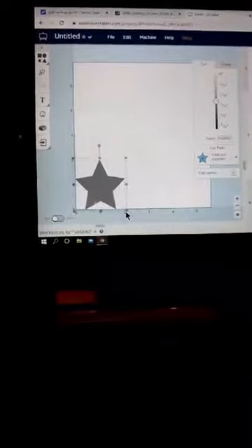Okay, now watch this. Now, this is 2.something inches. Okay? This is just not accurate. Okay? Please. And I tell people, and it's true, CNC machines were developed around the metric system. CNC machines do not play well together with inches. Okay? And learn to use millimeters. Do not try to convert in your head.